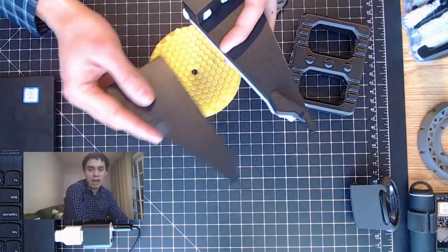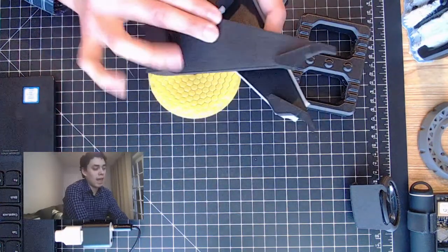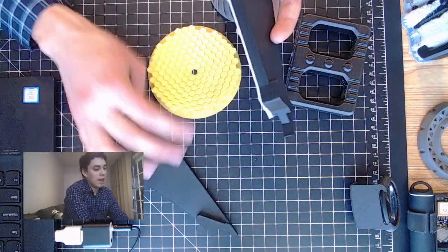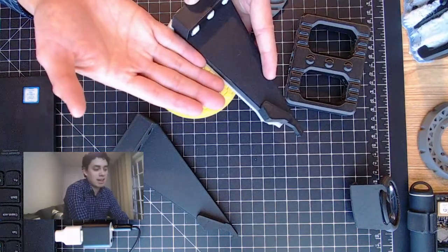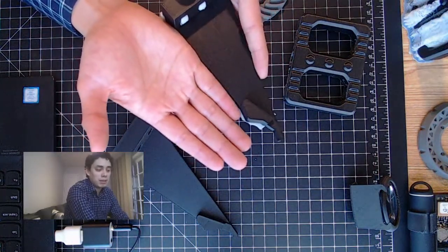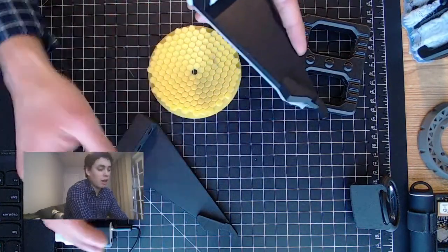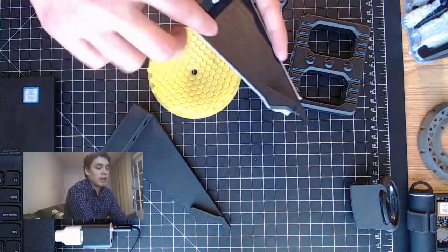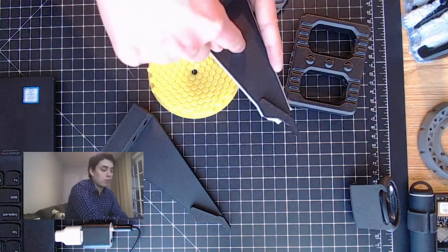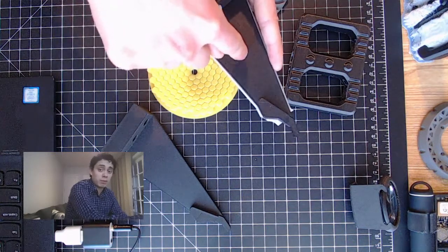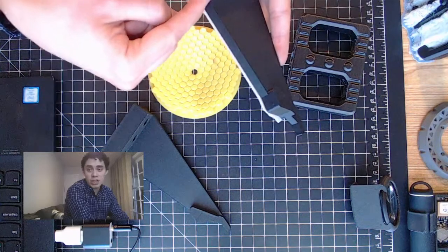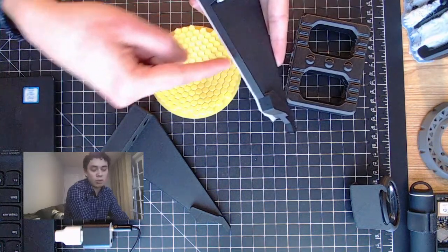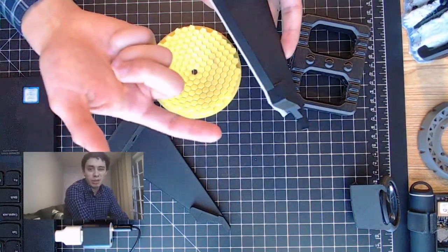I don't have the other half of it, but it's essentially half of a gripper element, right? And this part, you can already see by the raft itself, was printed flat on its side. This means that all of these layers will have a greater resistance to force being applied from the top than from the sides. Although, we have to say, it's a very shallow part, so there's not a lot of area to apply a force laterally here that can shear my part.